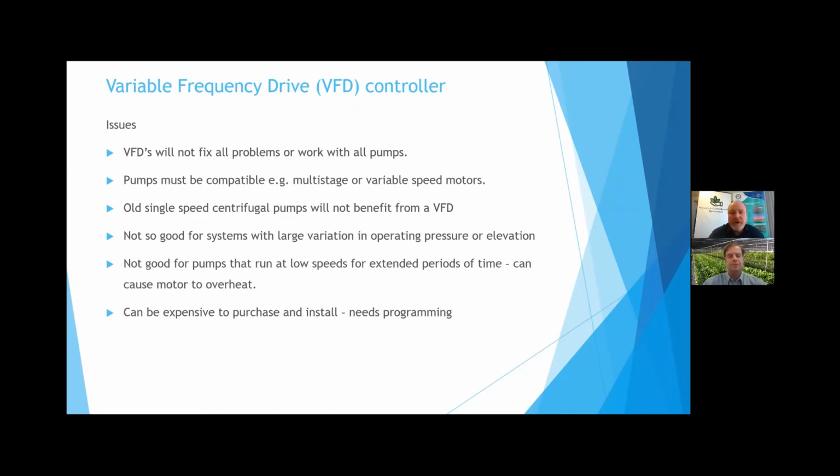If you've got an old single speed centrifugal pump, a VFD may not be the best way to go, because some of those old pumps just weren't designed to be manipulated that way. Also, the situation needs to be assessed by a pump specialist to determine if the VFD drive can be installed on an existing pump.